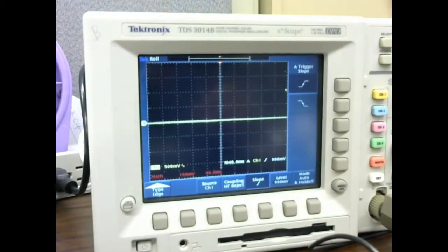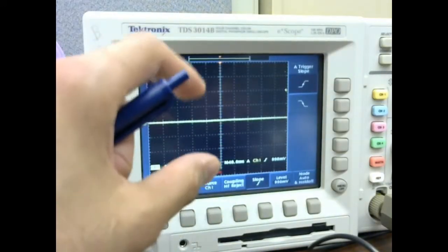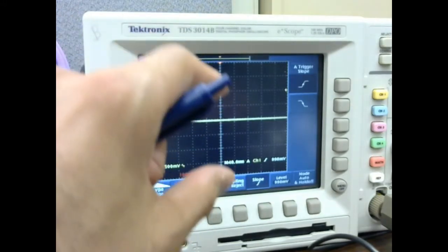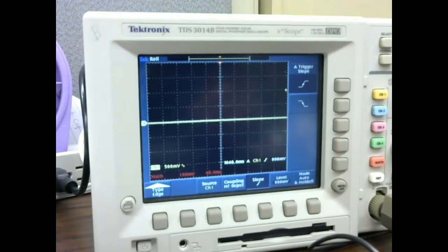So here we hit it, positive voltage happens first, and negative voltage happens second, because piezoelectric materials are springs. So you compress them and you let them go, they're going to overshoot, and they're going to come back down. They're actually little springs. All materials are sort of like springs. You don't normally get to see this effect, except that this is very sensitive because we're using voltage sensing.